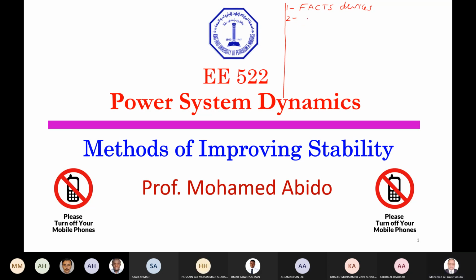Speed up the fault clearance. Yes, of course. If you have a faster circuit breaker, if you can detect the fault very quickly, this will definitely improve the stability, and again, you will not reach the critical clearing time. You are far from the stability verge or stability limit. So you can have a faster circuit breaker, faster relays to detect the fault.